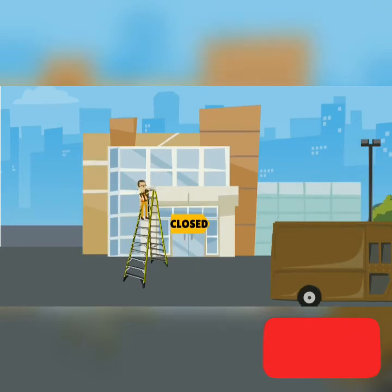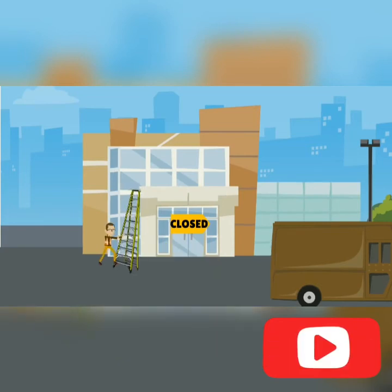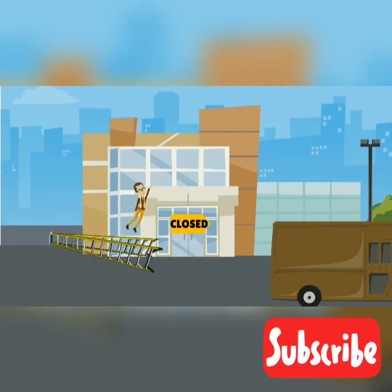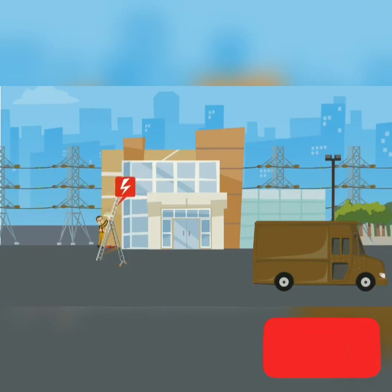When working from a stepladder, keep your hips within the two vertical rails. Reaching too far to the left or right could cause the ladder to topple. Never lean a closed stepladder against a wall and then climb it, because it can easily slide out from under you. When working on or near electrical equipment, the ladder must be non-conductive. Use a fiberglass or wooden ladder. Never use an aluminum ladder near this equipment.